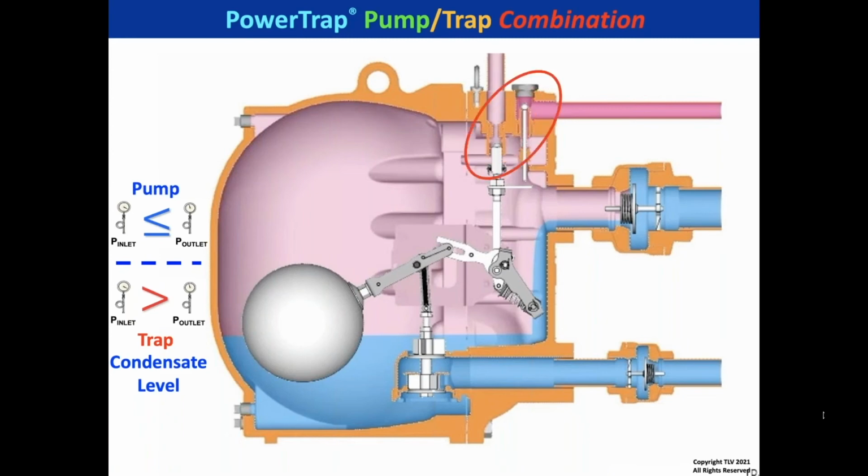Look at the valve train to the right. There is the motive valve that's going to bring in the steam pressure to pump it out. And we want to close that cavity off at that point so we can pressurize the body. So we're going to close off the exhaust valve, which is normally open for venting. And that's the operation. So please take a look at the animation.